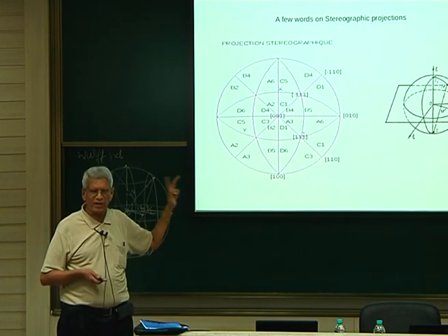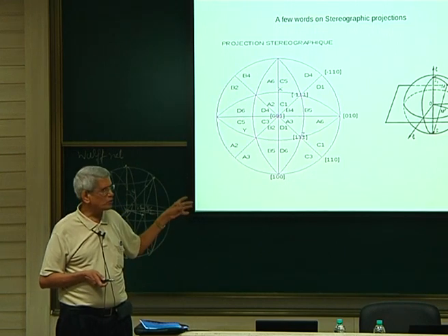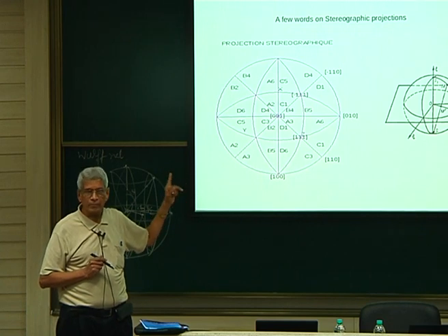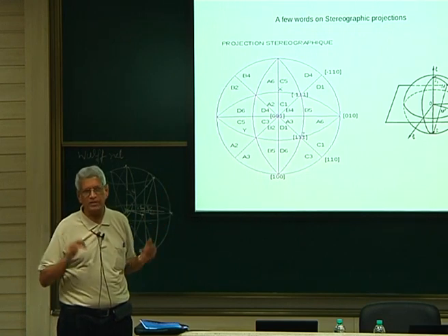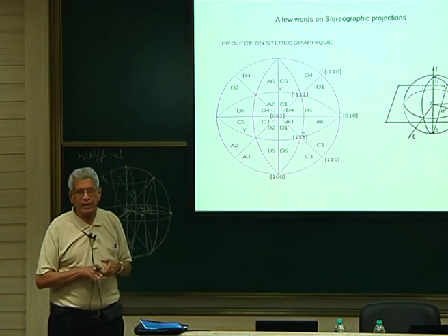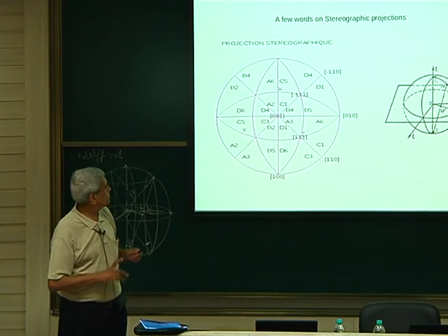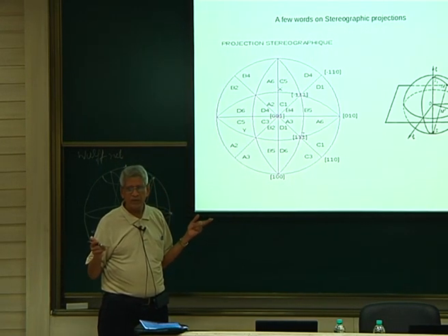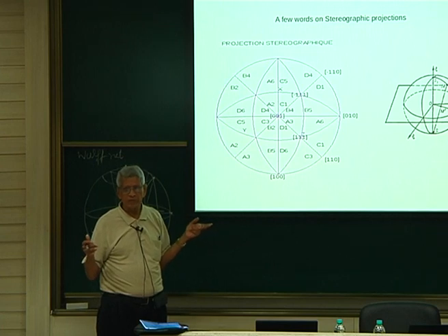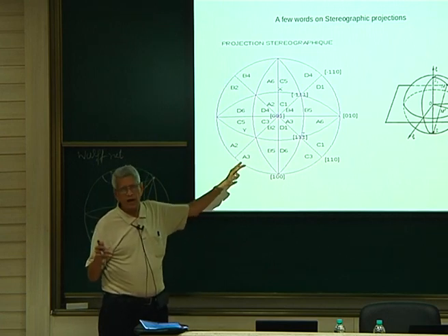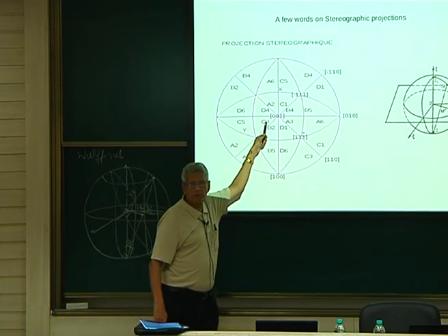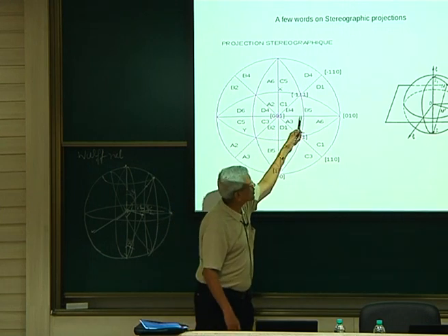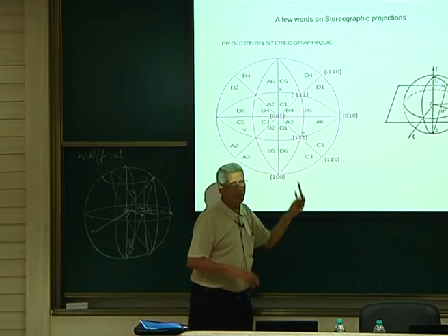So it has a lot of application in crystal plasticity also, but this stereogram is for a cubic crystal. Suppose you are working on a crystal which is non-cubic, we can find out the angular relationship between different planes, if you know the c/a ratio. Then we can draw similar types of stereograms. These are called stereograms for the 0 0 1 projection. From this we can draw stereograms for 0 0 1, for 1 1 1. All these things could be done.